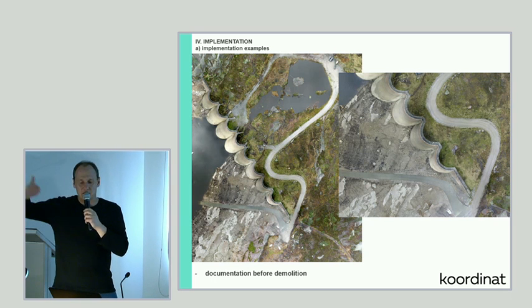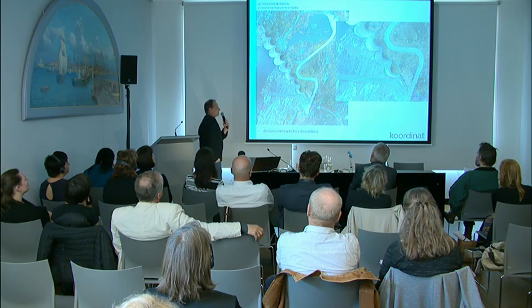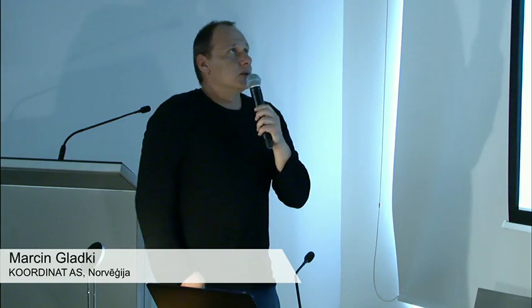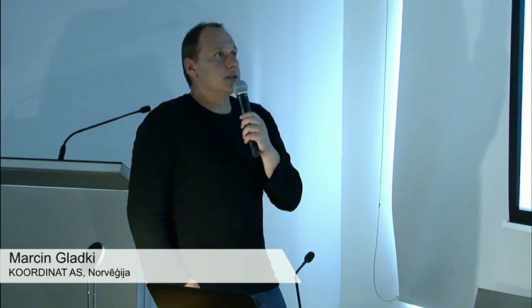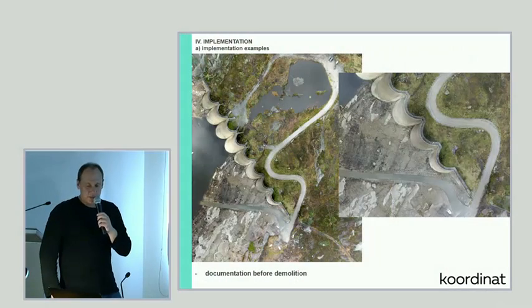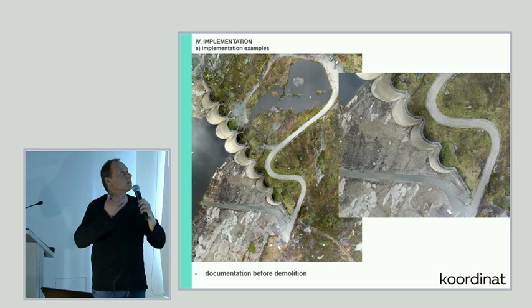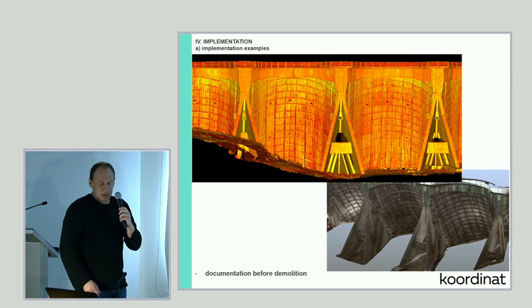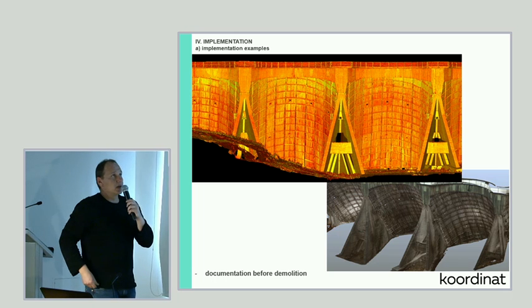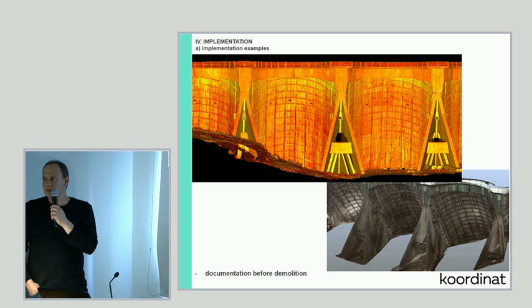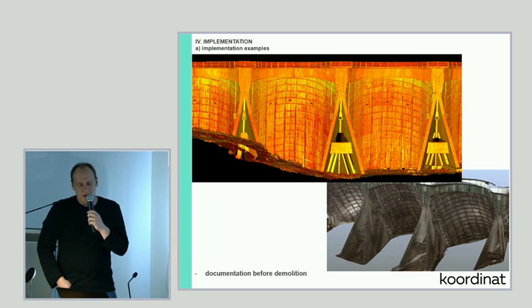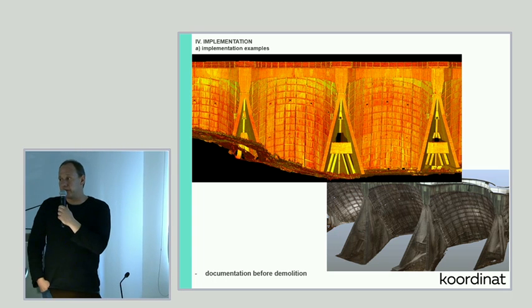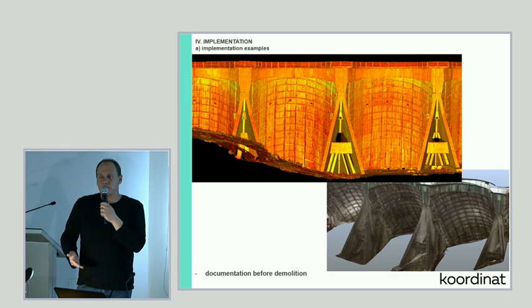I mean, the series of overlapping pictures, like Agisoft PhotoScan or many more, Pix4D, for example, or another type of that kind of application. And this is the perfect way to use it, just to create the DTM and a rough model of the object from the top. But inside we have a very regular wooden pattern from very straight timbers, and that's the place where photogrammetry actually failed. So scanning was definitely the better solution to document it.